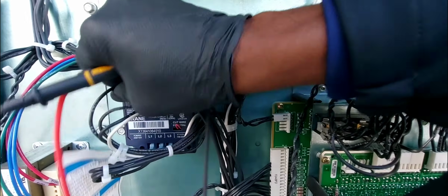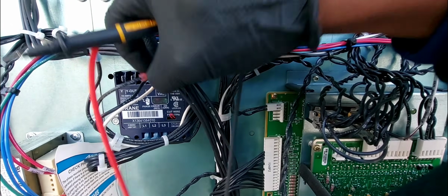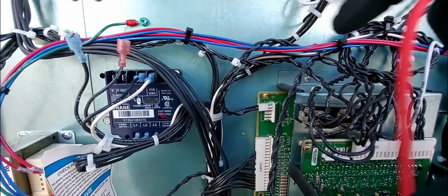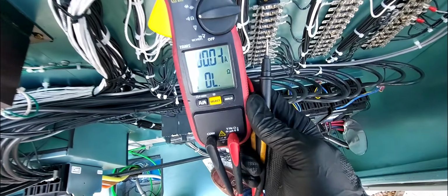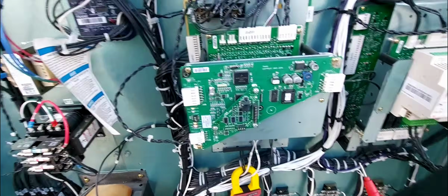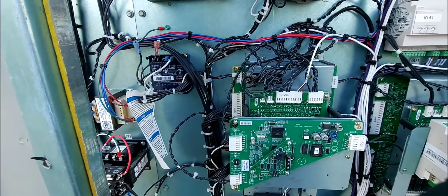Also, Trane, I don't know why they would do that, because it's rather confusing. You arrive at the unit and there's an external stop. So I'm in continuity. I'm just going to check the contacts on the phase monitor to see if they're closed. So I'm in external stop, and I'm not looking to check the phase monitor. All right, this should be a separate input.